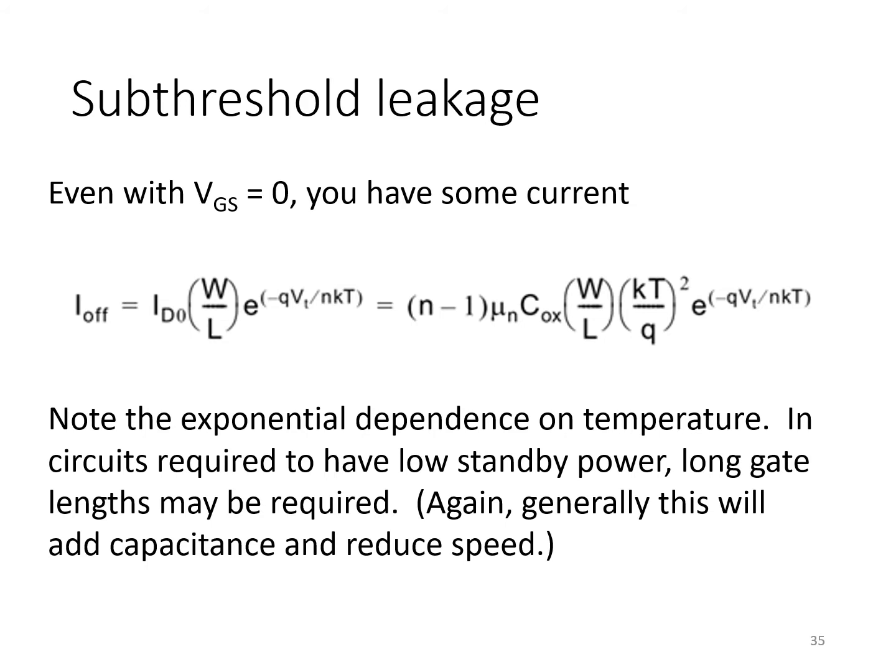Now, the nomenclature I prefer to use is to refer to subthreshold current as the current that arises whenever V effective is around 0, that is, whenever VGS is around the threshold voltage or below. And I specifically refer to leakage current as the current that arises when VGS is 0.